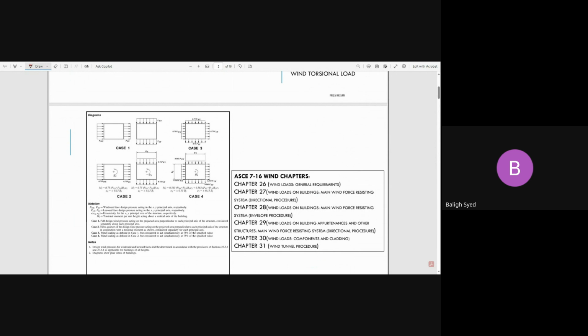So you guys have been doing a lot of residential structures, townhomes and that kind of thing. What is the mean roof height? Usually for the residential structure, 35 to 36 feet roof mean height, right? Townhomes are also the same thing, usually 40, 41 or 42 feet, right? So these structures are not prone to the torsional loading as required by the code. The code requires torsional loading on every single structure, but do these two structures qualify? No, they don't qualify for the torsional.